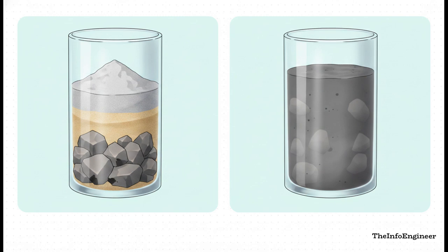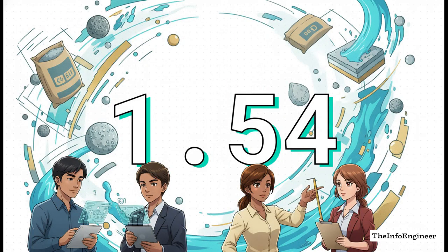Because of this, you actually need significantly more dry material to yield 1 single cubic meter of finished wet concrete. Okay, listen up, because this is literally the ultimate quantity surveyor trade secret, the 1.54 dry volume conversion factor. This is the exact number that separates the seasoned pros from the amateurs. If you only remember one single number from this entire explainer, make it 1.54. To get your required dry materials, you must take your calculated wet volume and multiply it by 1.54. It is the absolute bedrock of manual concrete estimation.